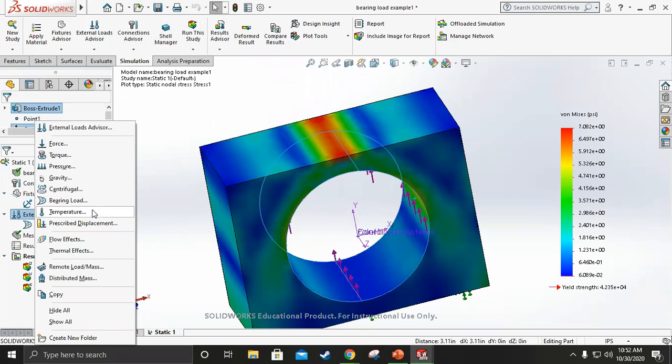What's good about SolidWorks is that there's different ways to do things. For example, pressure and force could technically be used as the same thing. So you might find a way to completely ignore force and just use pressure. That's up to you. I highly encourage that you do simulations on your own.